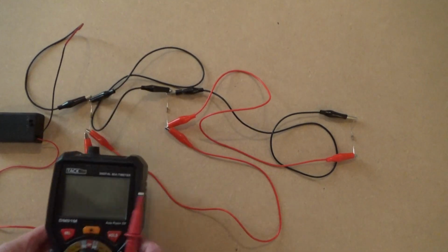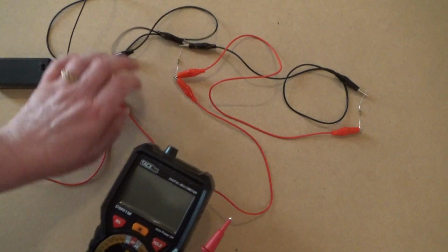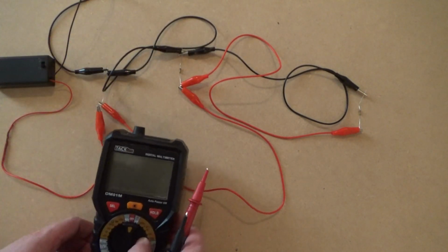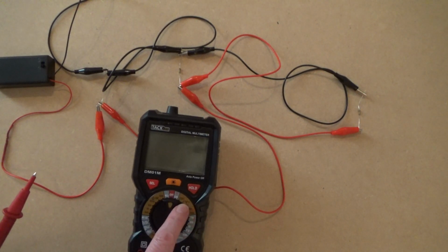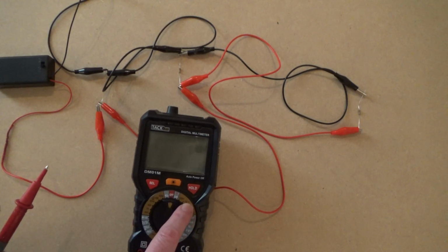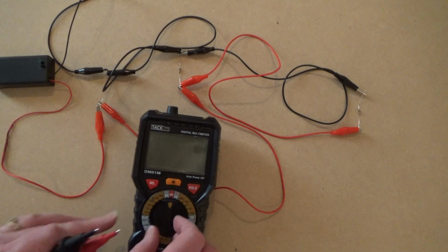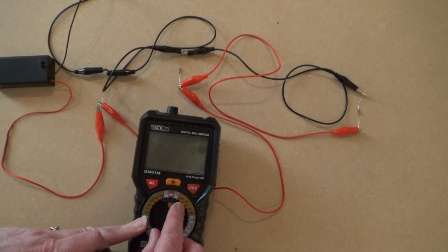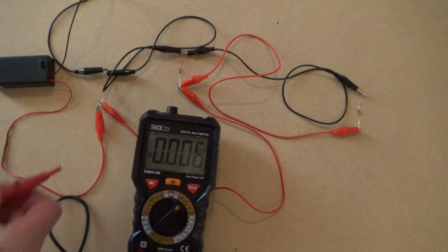So I'm going to turn this and move this up just a little bit more so I can get everything in view. Try and get everything in view where you can still see it. Okay, that looks pretty good. So I'm going to turn this dial to, on this particular meter, this V with the line and dashes there, that is DC, okay? So I'm going to turn it to DC volts, and I'm assuming that I should have somewhere around 3, so I'm going to go ahead and turn it up to the 6. And that should give me